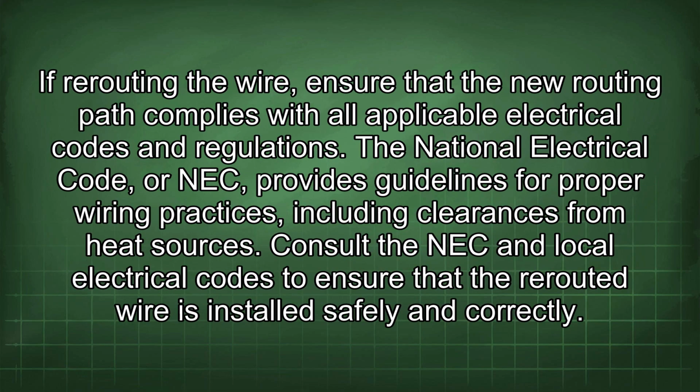If rerouting the wire, ensure that the new routing path complies with all applicable electrical codes and regulations. The National Electrical Code, or NEC, provides guidelines for proper wiring practices, including clearances from heat sources. Consult the NEC and local electrical codes to ensure that the rerouted wire is installed safely and correctly.